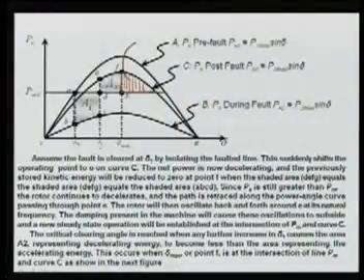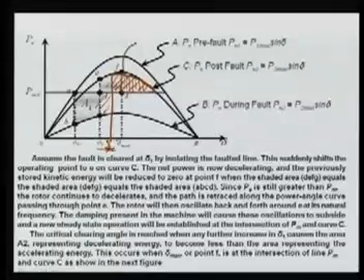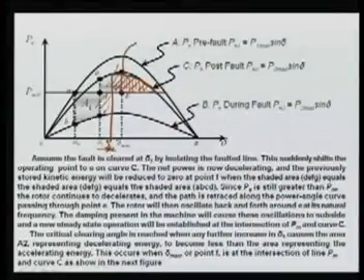So what happens, there is a possibility that the fault, even if it is not cleared, then delta 1 less than that or at delta, so this value will keep on increasing. Let's suppose your delta is increased here, so this machine will go up, oscillating here, and this complete area will be equal to area A2. Then this angle delta C is called the critical clearing angle, meaning the angle beyond which, if the fault is cleared, the system will be unstable. If it is cleared before that angle, or you can say that time, then your system will be stable and there will be no margin, that is the critical clearing time.